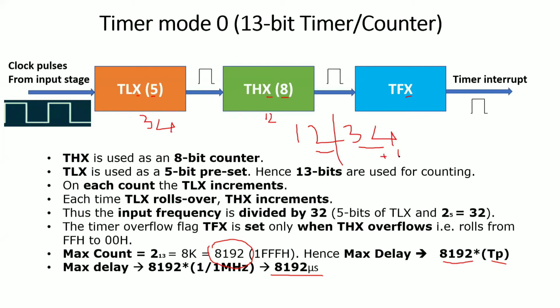If you increment the lower byte, you are adding 1 to it. So 1, 2, 3, 4 plus 1 becomes 1, 2, 3, 5. If you try to add from the higher byte, you get 1, 3, 3, 4. That is obviously wrong, if you know the mathematical basics. So to increment, you need to add the 1 to the lower byte. That's why the lower byte is attached first and then the higher byte. After incrementing this value, it passes the carry to the next one so that you can get the next values.